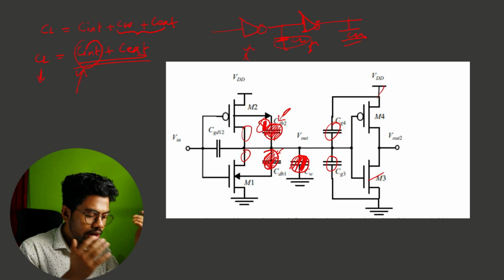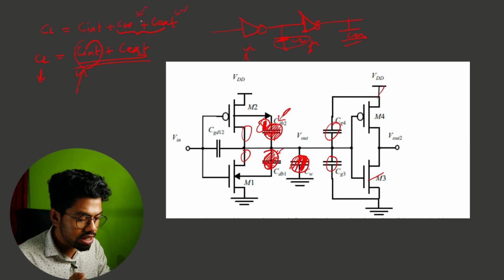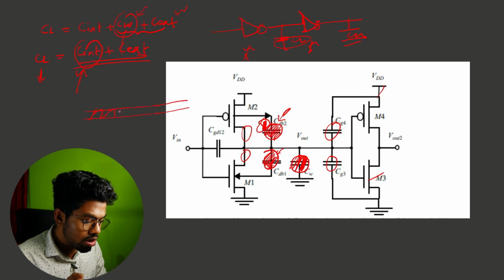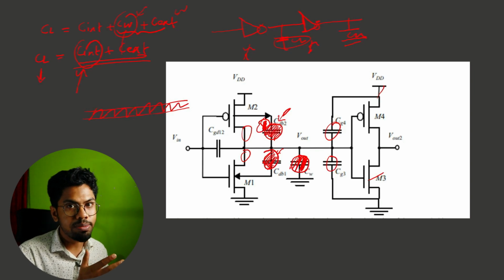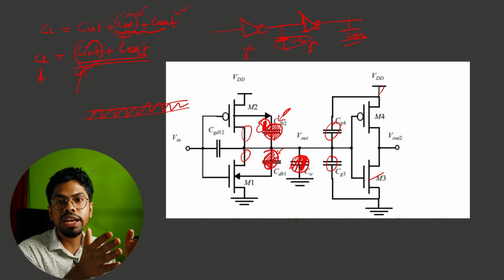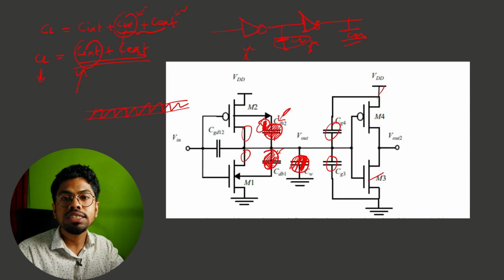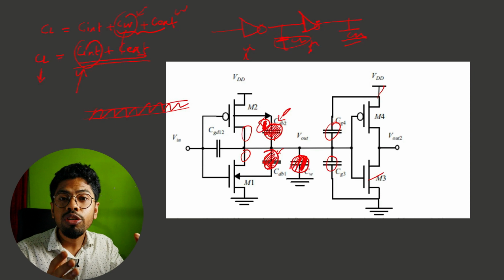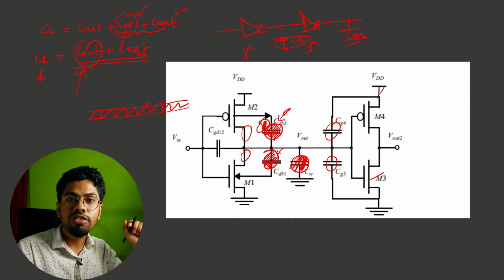And if we have control over the wire, we do the same thing. For example, your CW: if you have a long connectivity path between two circuits, it will increase your capacitance, so we try to reduce those paths. These are very important points which you can explain to your interviewer, how you can design an inverter looking into the performance or speed of your inverter operation.